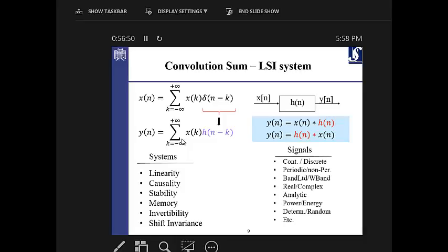You have power signals and energy signals. I think it should be clear in the name. When we say power signals, it means that the energy is... exactly. So the power signals are those which their energy is just definable in a period. In a period of time, the energy is something known or limited, but if you increase the time, then the energy goes to infinity. But the energy signals, they have limited energy. Okay? So now tell me, the cosine signal, is that the power signal or the energy signal? Exactly.